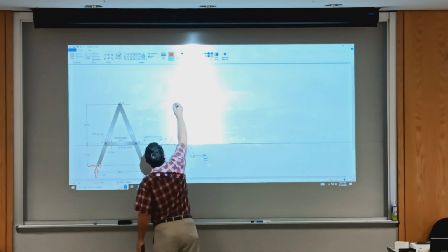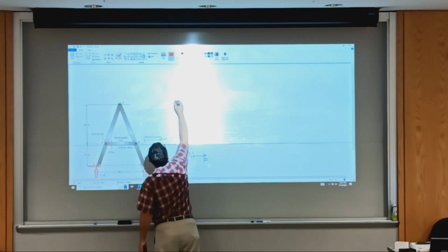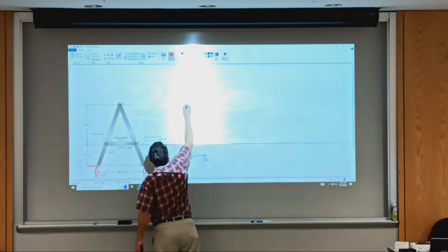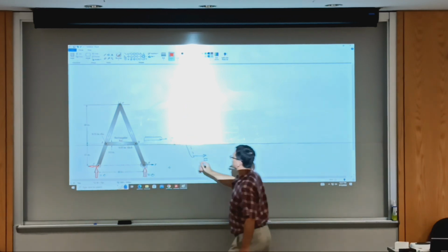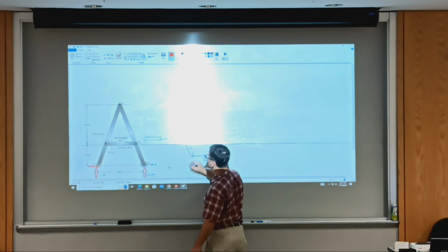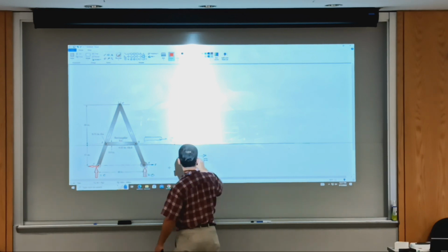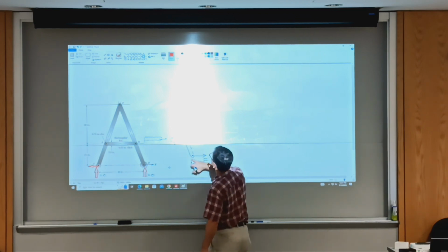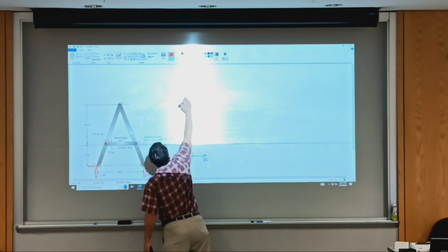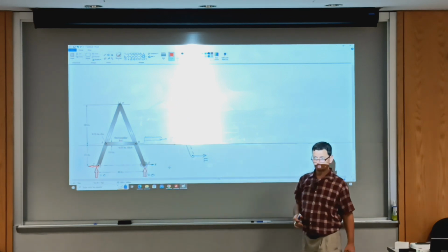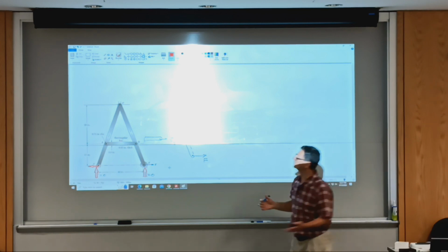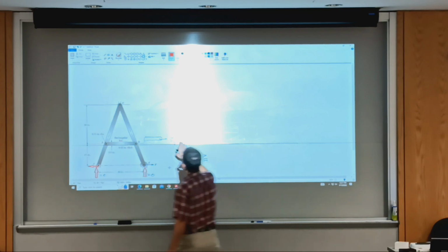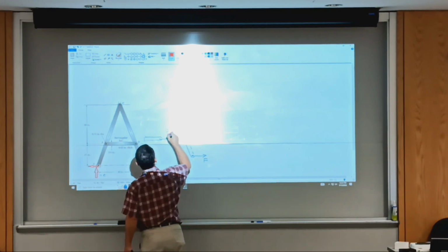And then we have a pin which, removed from its mount, has two components. Will be RC vertical and RC horizontal. Okay. This was 0. I have a pin now. I removed the roller. Have a pin. This force, never named it, should show here, but it's 0. So it tells us that this other force is 0. Okay. Does it make sense? So again, we don't spend time with useless little analysis when the result or the effect is clear. So this was the FBD.